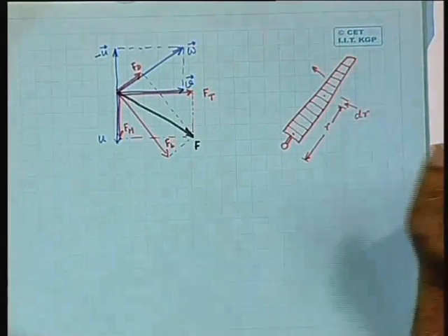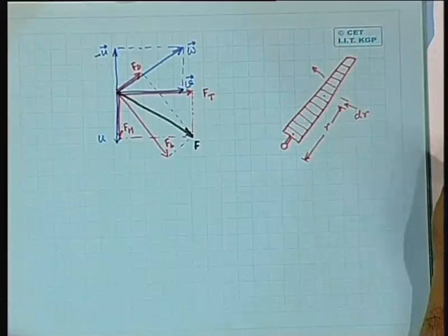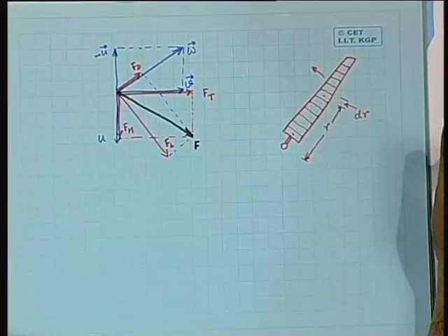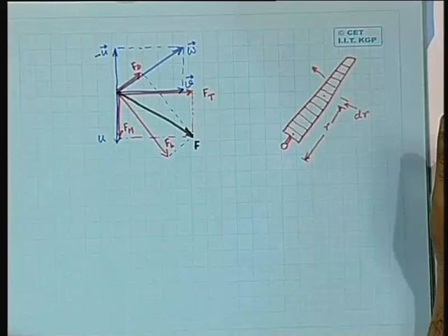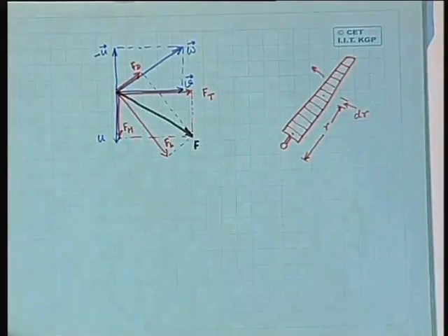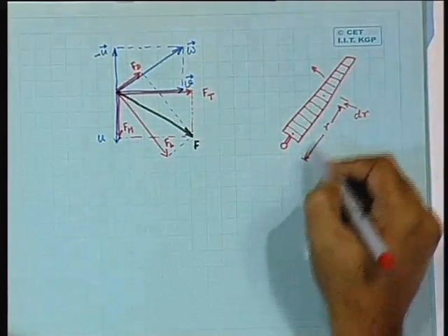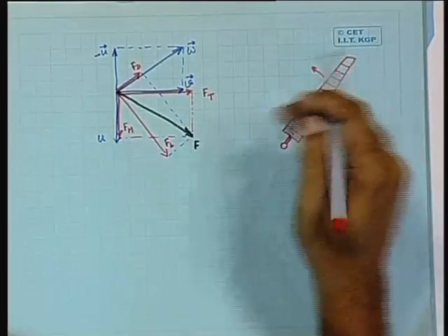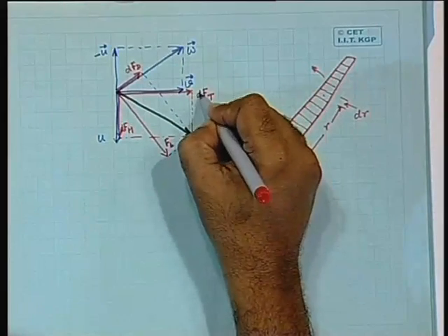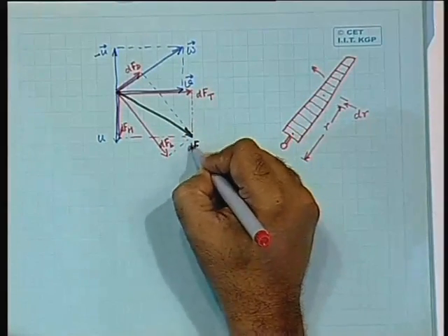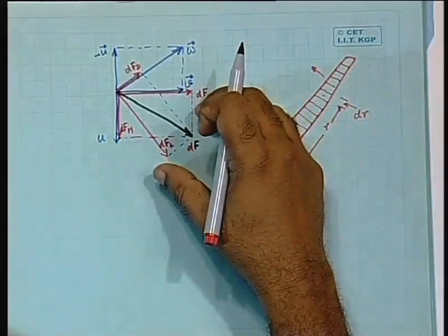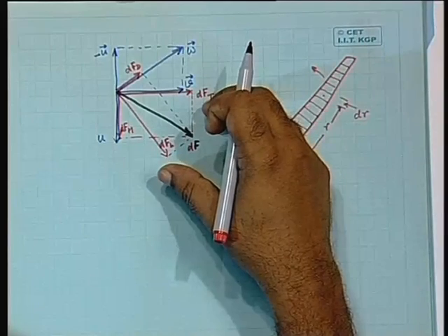Now what calculations? The calculations essentially start from the expression for the FL and FD. What is FL here and FD here? Normally, since these are all elements, these are denoted as dFD, dFM, dFT, dFL, dF and all that. Why? To signify that these are related to the blade elements, not the whole blade.